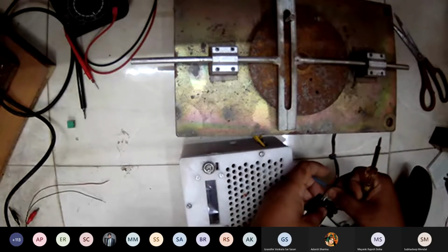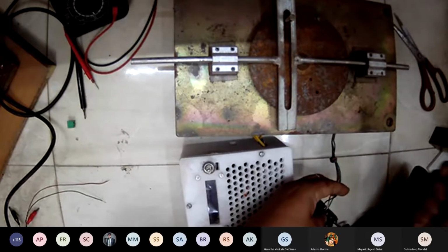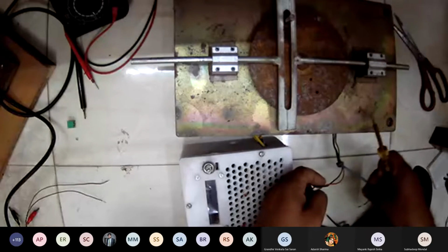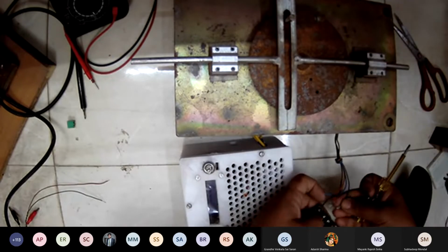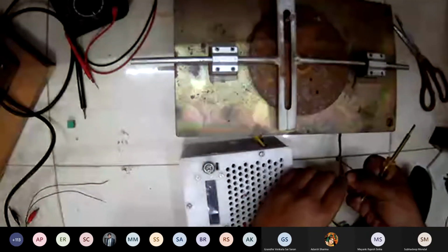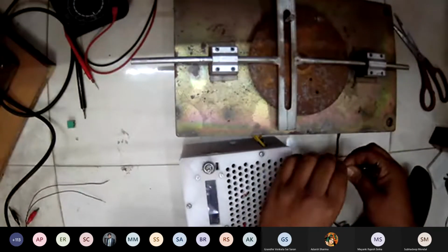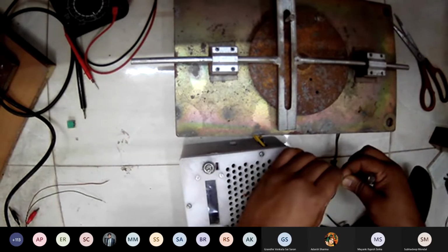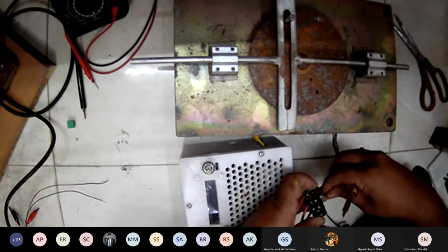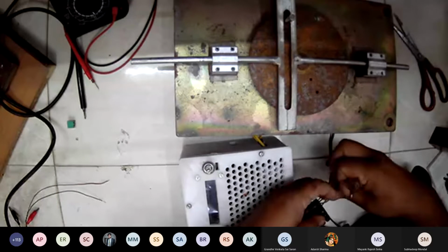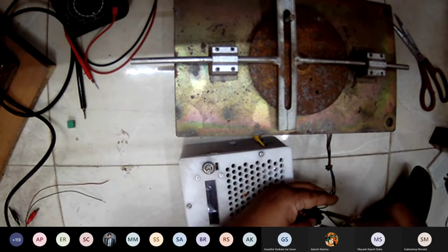It's only once the home position is known and the gear ratio of the tooth belt is known, then you can simply drive. Do you understand? So you don't need any encoding. The encoding is all natural. One step, so 200 steps per revolution. If you have one step of the stepper motor, one pulse, how many degrees will it go? 1.8, correct. That's a very small angle if you think about it, so you really have a good precision already going on.